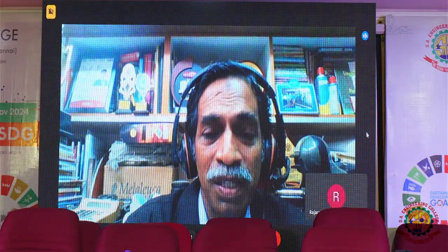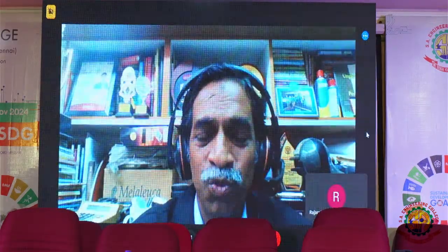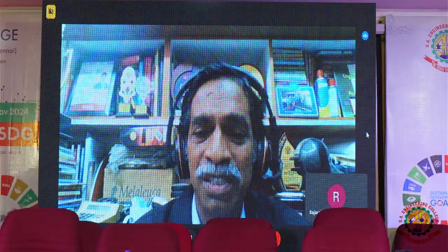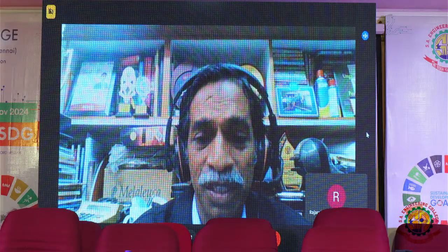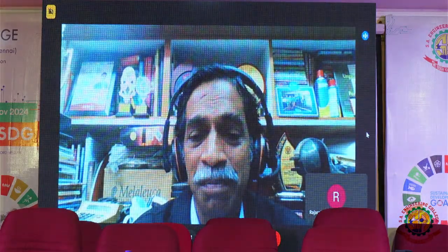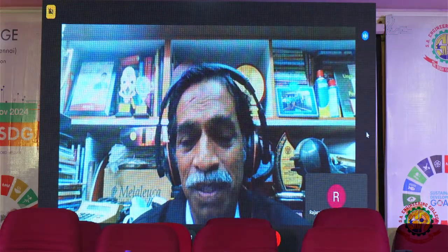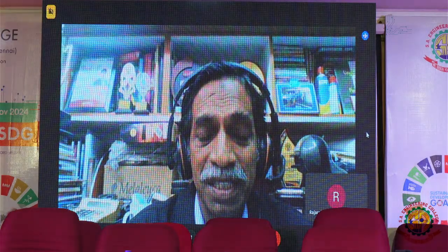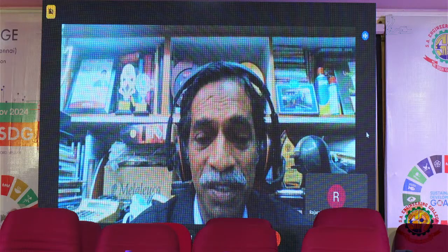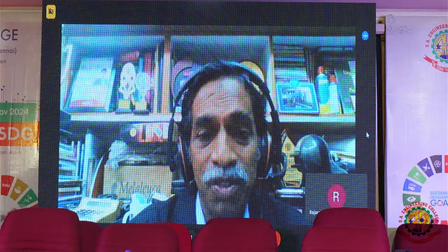So why a wireless sensor network? It has a short receptive period, like 36 to 48 hours, like one and a half days to 2 days. Then a remote monitoring system for this is good. That means you don't need to climb the tree. You monitor certain parameters. Then if you reach a certain threshold value, you can send the people to go and do the pollination. So this is the architecture, the three-layer architecture. This is your sensors, this is the middle layer, and this is the application layer. So this is how it works.